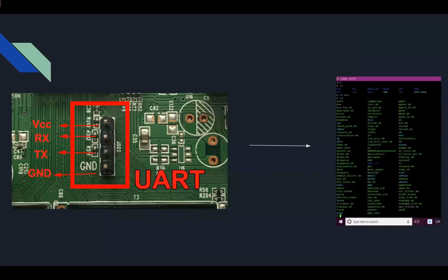The thing about this is it's a lot easier than you would expect, because there are USB devices that you can just plug into the side of your laptop that have like 4 pins that will just plug into those headers right there and get you a Linux shell on your embedded device.